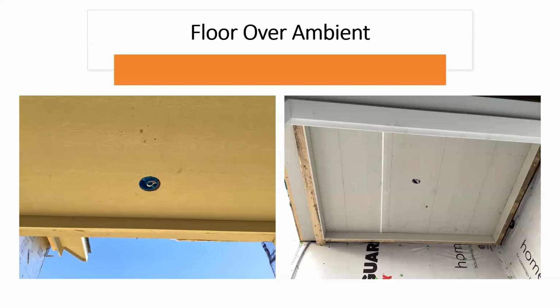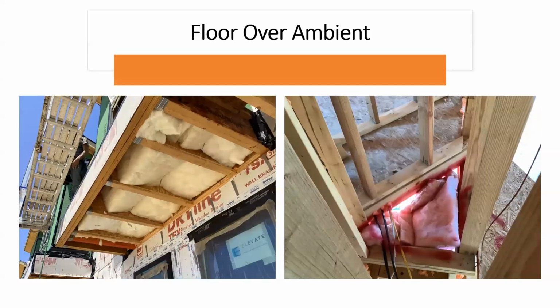They go around and just start putting up cornice boards because they're trying to stay on track with scheduling. And then the insulators haven't come out. It's either not insulated or it was pre-insulated, but you don't know if it was done correctly. And then the cornice board goes up. It has to be removed to actually verify compliance. In both of these pictures, it's incorrect.